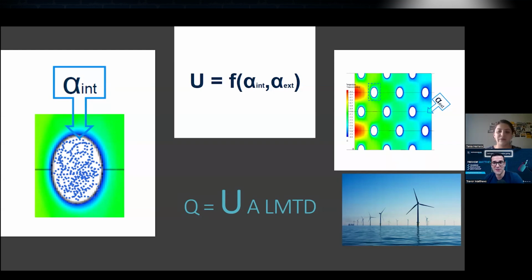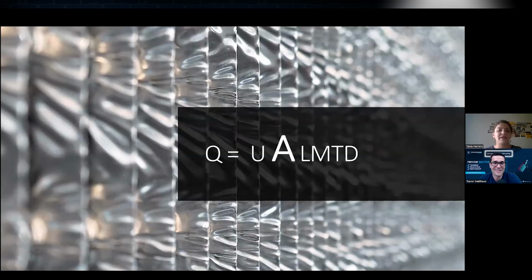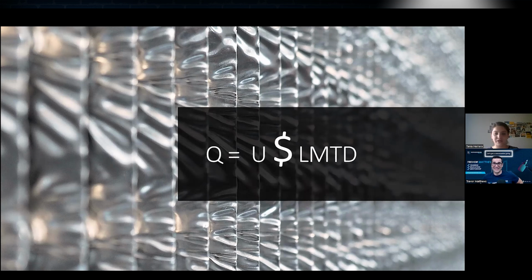Excellent. Let's keep going. Okay, so now I'm going to talk about the heat transfer area. In our evaporators, as I mentioned before, 90% of the heat transfer occurs in the fins. So if we want to increase the heat transfer area, we can always add more fins. But this means more material, so you will have a more expensive heat exchanger.